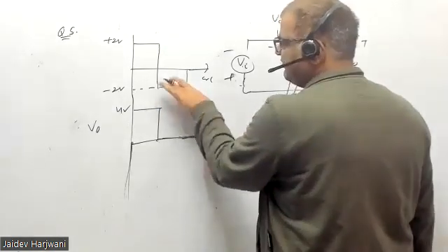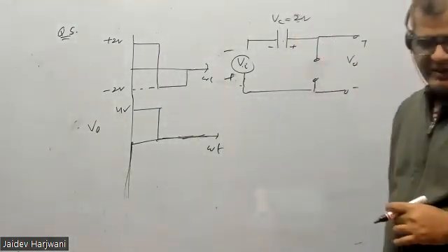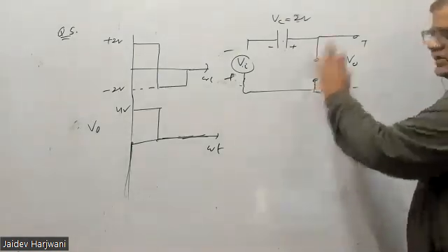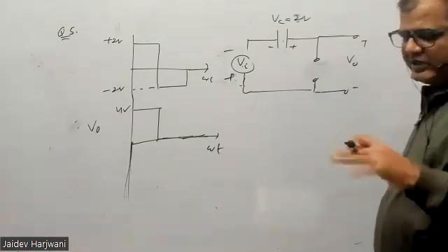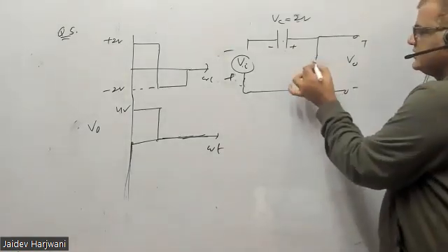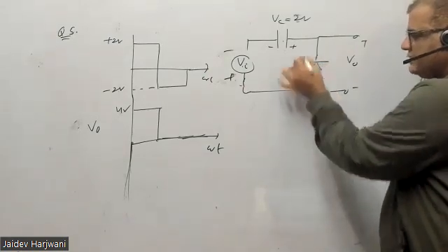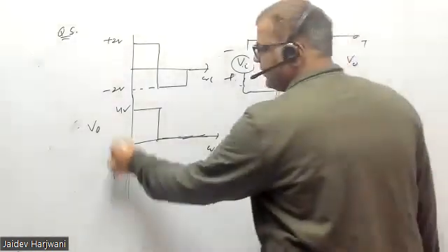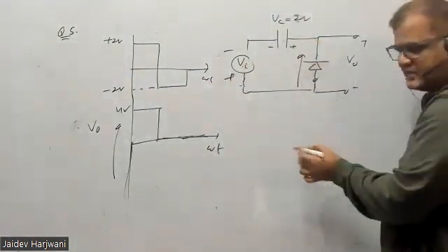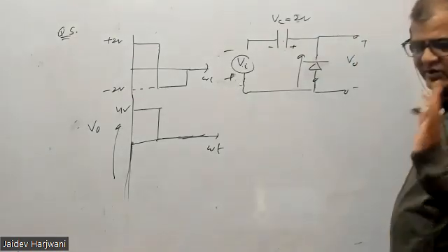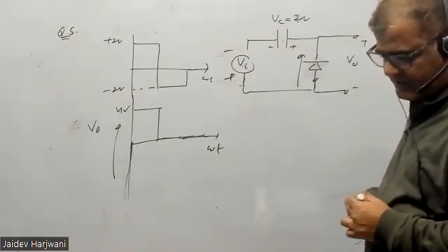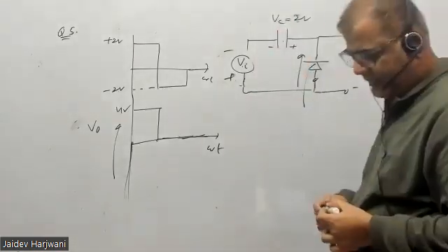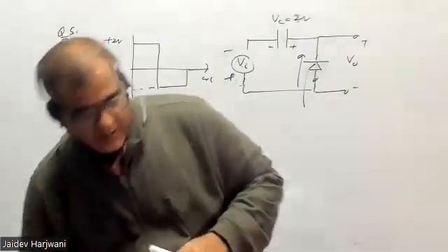So this is basically the positive clamping. Your signal will always get clamped in the direction of the current. You always remember, if you get confused, earlier this was my diode, and this is my current direction. So obviously my signal will go up. If my current direction is like this, my signal will go down. You check all the cases we have done in the class. It will always follow the current direction. Now current going up, the signal will go up. That you remember. Is that clear?